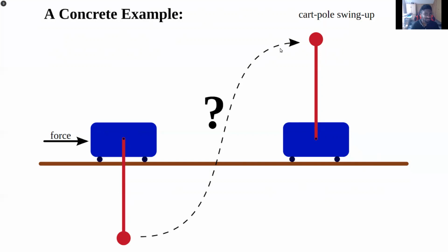And what kind of trajectory are you going to use? And mind you, the only force we are exerting is the force on the cart itself. We don't have any motor or actuator here at the joints of this pendulum. And so we rely on the dynamics of the system to come up with a trajectory to get it to be vertical. And so this is an under-actuated system because you're not controlling the whole system, only a subset of the system variables.